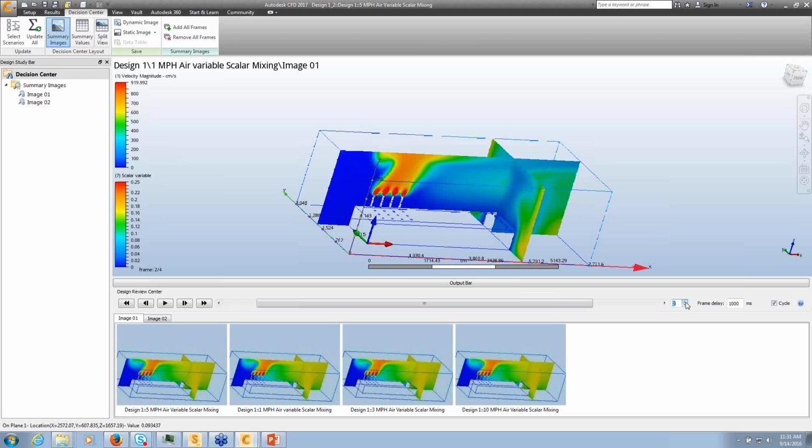When the air velocity is quite low, 1 mile an hour, probably our bounding box here is not large enough because you can see it being basically chopped off at the top here. The air wants to go up higher, so probably what comes in here is not a very accurate representation. And this is 3 miles an hour. This is probably the box of outside air is big enough to model 3 miles an hour wind. But I think the 1 mile per hour wind is not too representative because a lot of it is going to want to go up further.